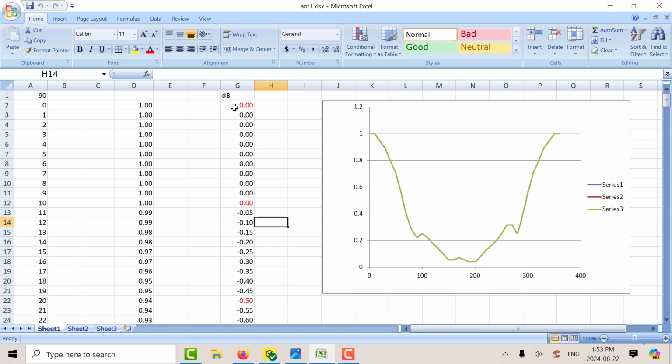Now these are relative gains in dB, so you have to convert that. For Splat, they want a voltage, your field voltage. So you have to convert that dB reading to a relative voltage. You take 10 and raise it to the power of dB over minus 20, so that'll give you that value.